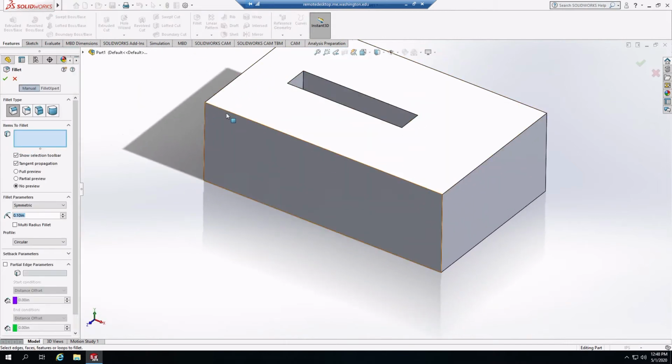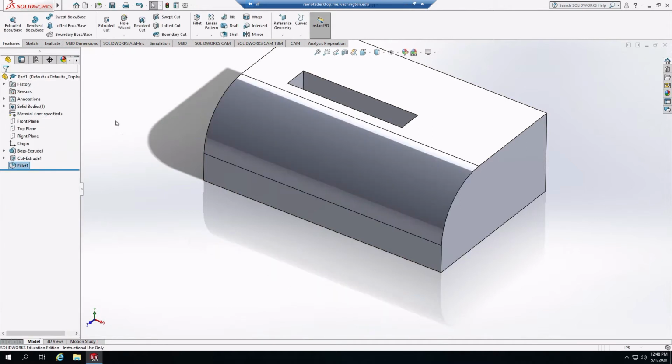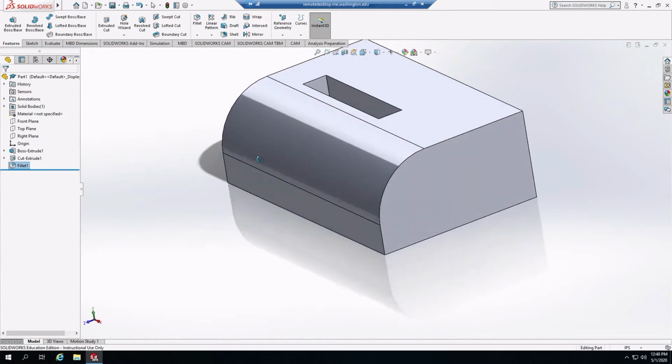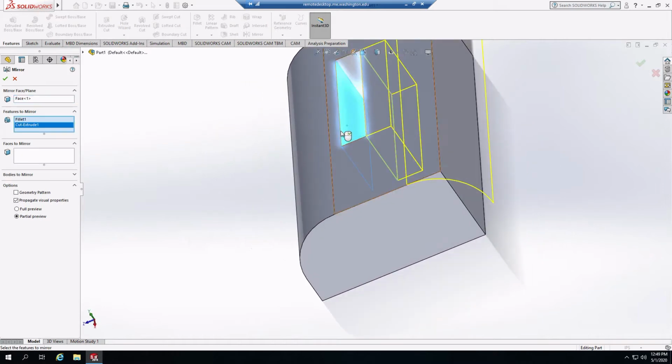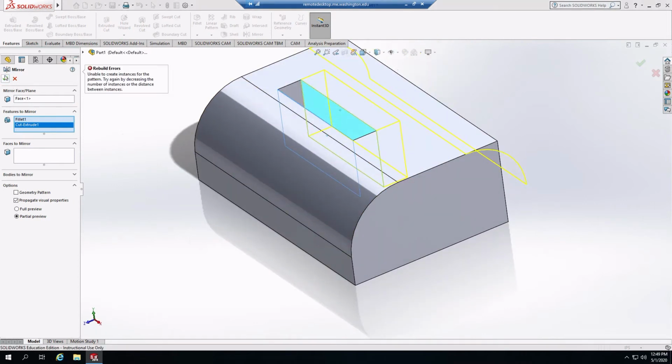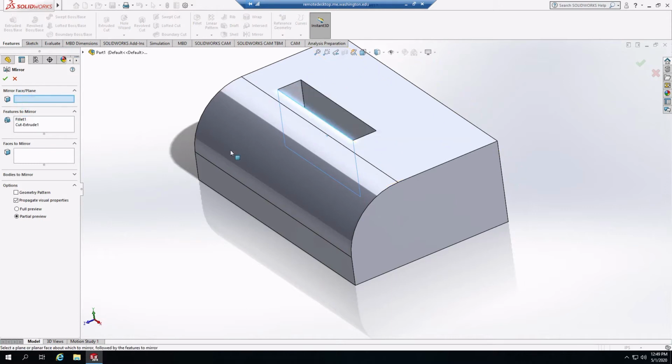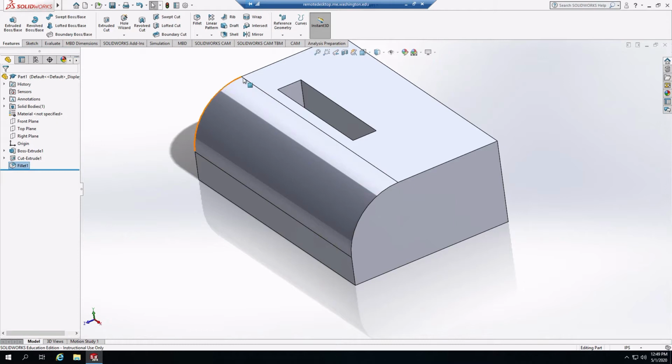You can also, from that same Features toolbox, do 3D modifications to the parts you've added, such as curved fillets on edges or straight line chamfers. You can also mirror geometry, so essentially duplicate across a line or across a plane what you've already done. Then you can also create reference geometry such as planes and lines to help construct items.